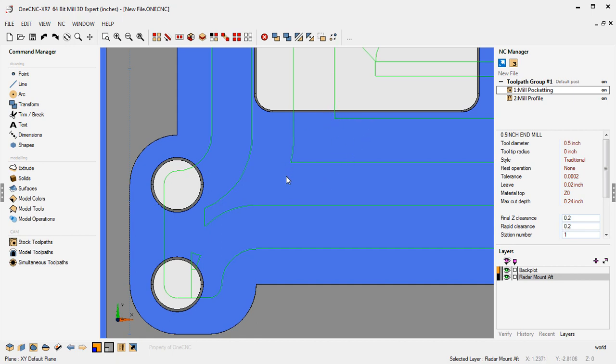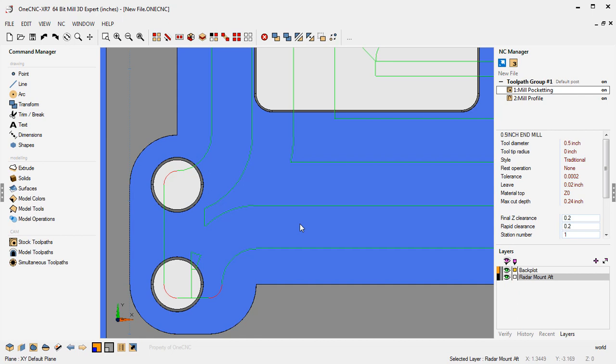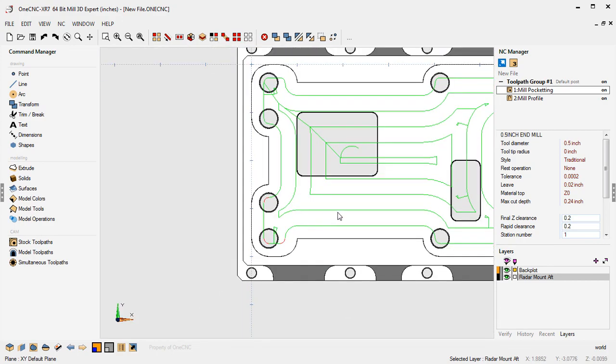And so when you're programming feed rates for this pocket operation, you're probably asking yourself, what's the safest speed that I really want the tool to make an abrupt direction change like this? Same with small fillets. You can see down here in the lower left hand corner we have some small fillets. You might have to ask yourself too, how safe is it to machine those small fillets? What's the appropriate feed rate for that? Well, in my example, I started off with 20 inches a minute.